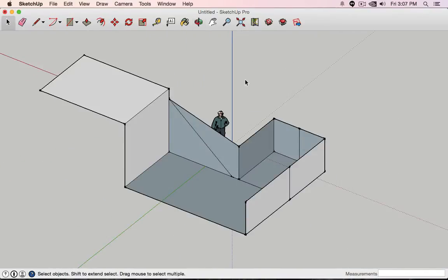There are different ways how you can delete something in SketchUp. So there's the eraser. If I click over a line and then release my mouse button, you see it removes those parts. So let me do this again. I click my mouse, paint over those edges, release my mouse button. Those edges are removed, and obviously then the face is removed.